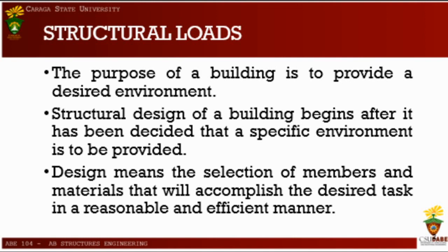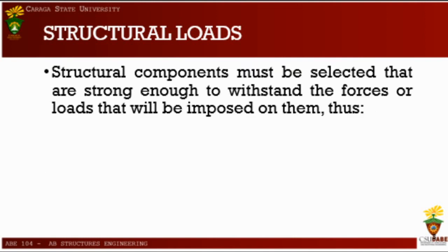With this, structural components must be selected that are strong enough to withstand the forces or loads that will be imposed on them. Thus, it must satisfy this equation: load must be less than or equal to resistance. So what does it mean? It means that if the load effect exceeds the resistance, then the structure will fail.